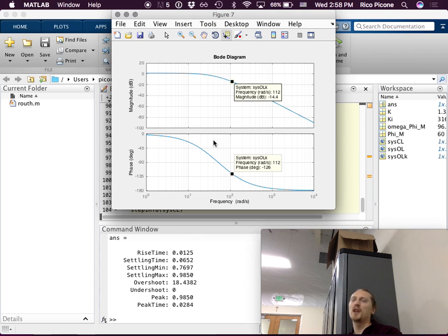So you can shape this diagram with that, and you can try to get the phase margin to be a certain thing, or the gain margin to be a certain thing. And that's really what all these techniques come down to, is shaping this. This is when your Bode plot sketching helps you, because you can start to think about how putting a pole here, a 0 here, is going to affect the shape of your Bode plot, instead of just ad hoc trying to shape it.